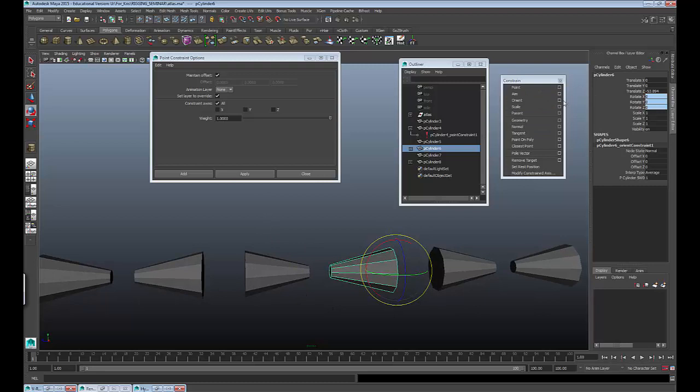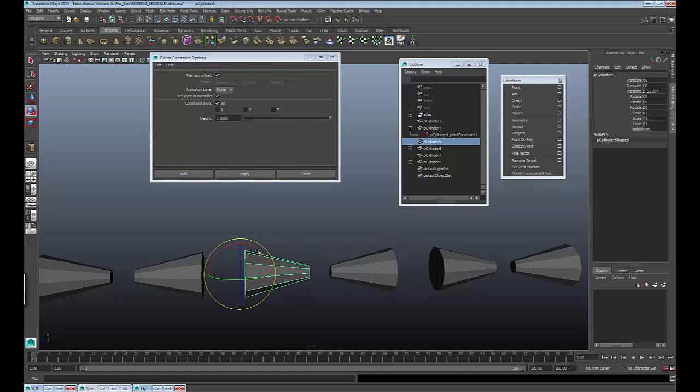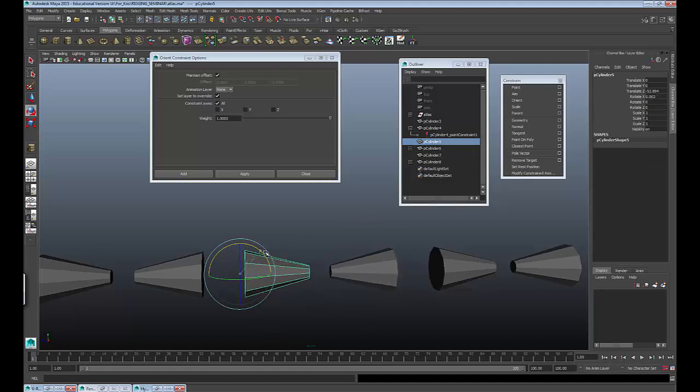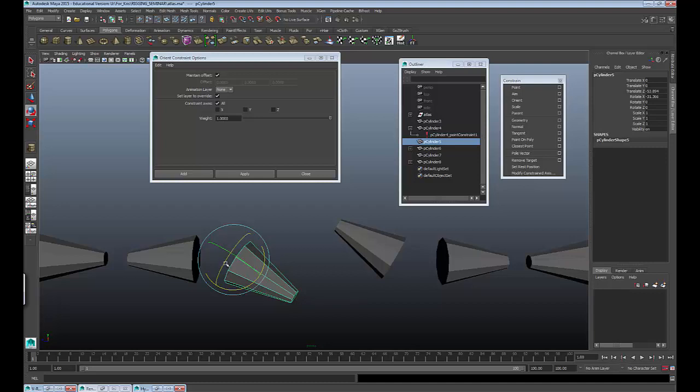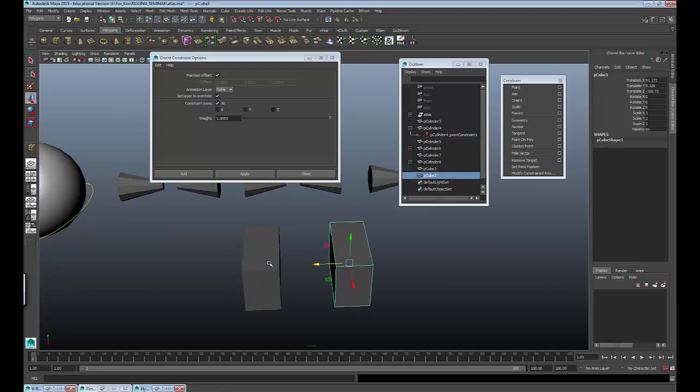Bear with me for a sec. So if I did want to do an exact mirror move, I would just have to make sure the pivot is aligned properly. Because technically this is doing the exact same rotation, right? If I rotate this down, this part is pointing down, this part's pointing up, this part's pointing down, this part's pointing up. So it is giving me the exact same rotation. It's just rotating from a different pivot on this object because they're facing toward each other. So it's a little bit abstract. If I had two objects with the exact same pivot and did the same thing, it's going to match exactly, right?